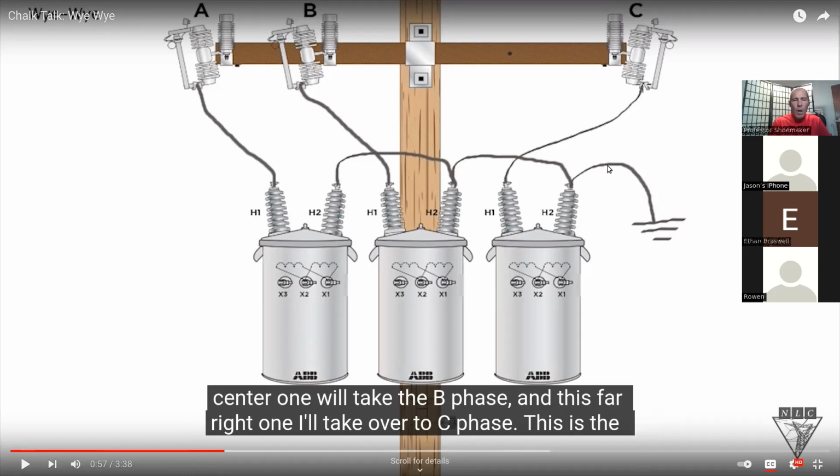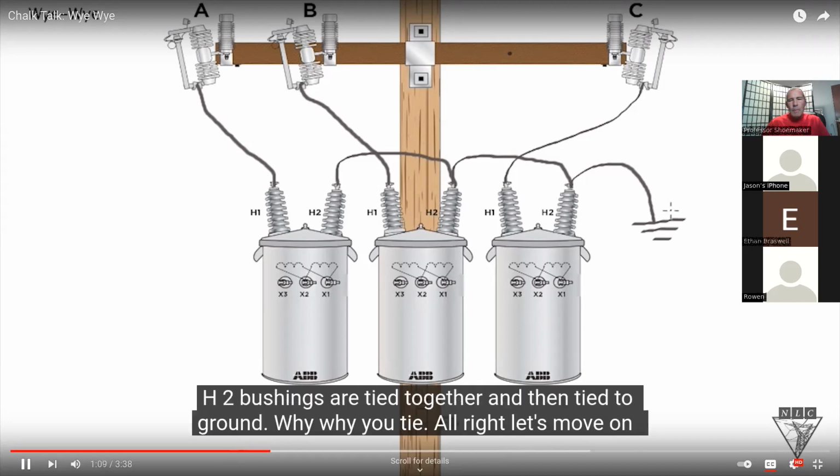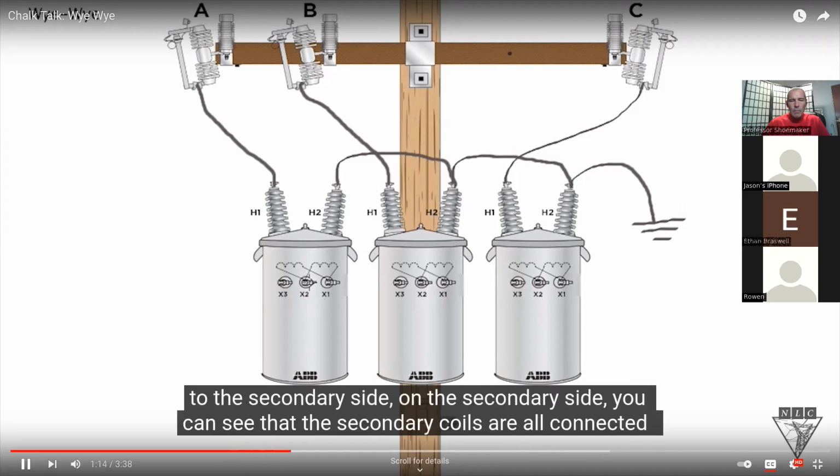That applies in all 3 banks. Use the same bushings. This is the connection on the primary side of a YY. H1 bushings each go to a phase, and all the H2 bushings are tied together and then tied to ground. YY you tie. All right, let's move on to the secondary side.